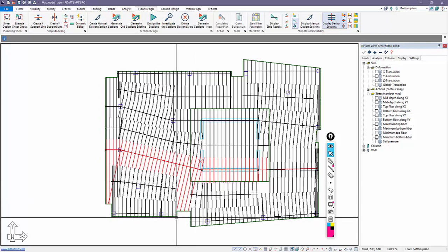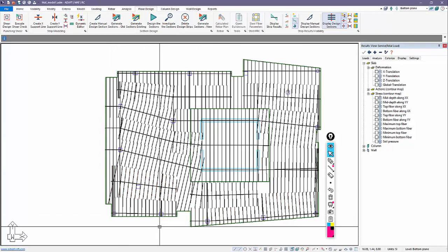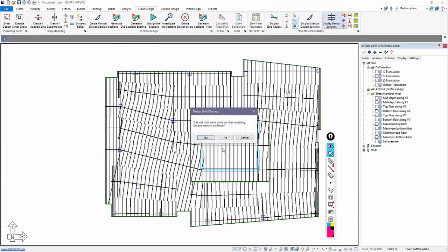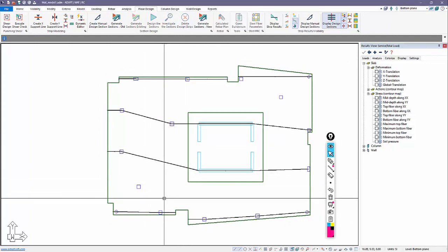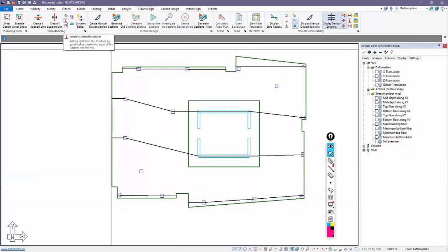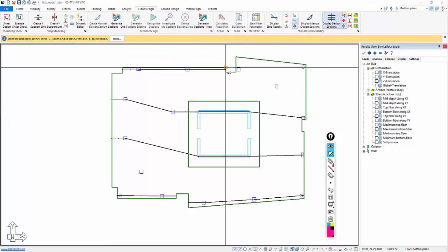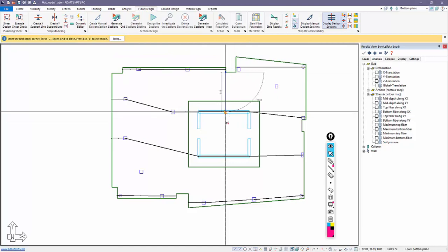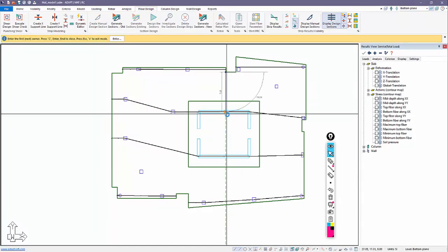Because this stops here and this stops here, there's a gap. And the middle strips are only replicated over the distance of the adjacent column strips. So one way to clean that up in the 2018 and previous versions would be to add what we call splitters. And I'll go ahead and use a splitter, which is really just a virtual boundary to generate, let's say, more expected middle strips, or to manipulate how the middle strips are being generated. So I'll add a splitter along this path and along this path.